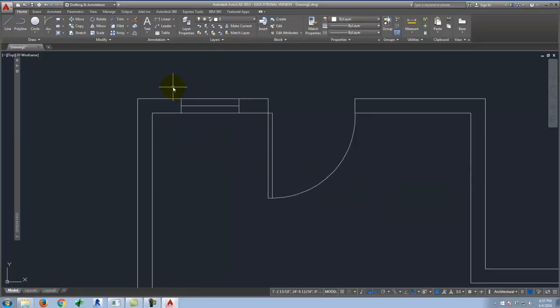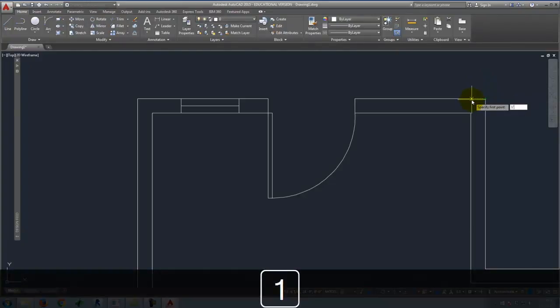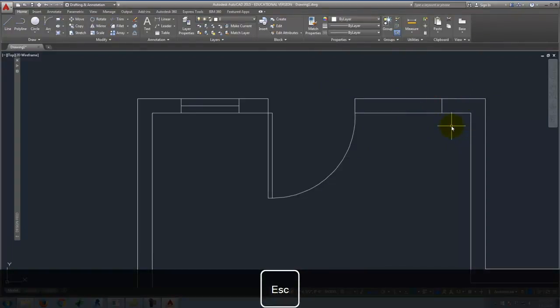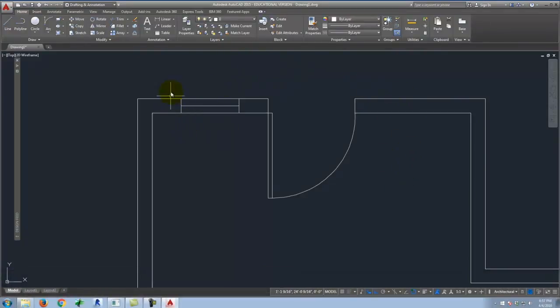So at this point, I now have one window that's drawn on this side. If we look at the floor plan here, I have a window that's on the other side. That's exactly the same in dimensions. So I could come over and reverse the process and draw coming over by 1 foot 6, and then drawing it, and then doing the offset and drawing it that way. But this is not as efficient, let me get rid of this, as taking this and mirroring it to being over here. So I'm going to select, and again, I'll select from left to right.